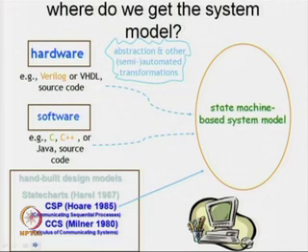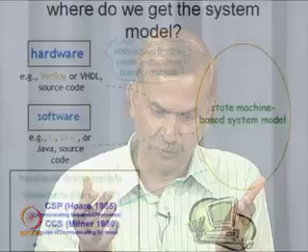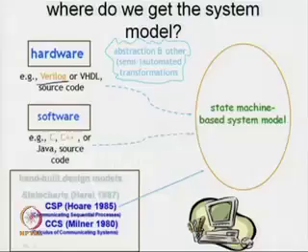Different people design the system in different ways, either hardware or software. Already I have mentioned that since I am going to talk about one verification method, it can be applied to all design cases, hardware or software. In case of hardware, generally we describe our system at the RTL level with the help of some HDL, hardware description language, like Verilog or VHDL. So, we can have those particular Verilog and VHDL descriptions.